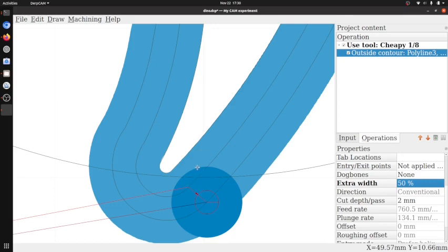So it's going to be doing this first of all next to the part, so hopefully the finish right up against the part is going to be increased because the end mill isn't under the same stress. It's going to go all the way around the part until it gets back to here, at which point it's going to traverse back to this side, push another 2mm down, and this time we're slot milling again, but the bottom of the end mill is now 4mm below the surface and the slot's only 2mm deep. So it's not nearly as bad as when we were just pushing round and round in the same slot. But it's still not perfect, right? Is there anything we can do better?